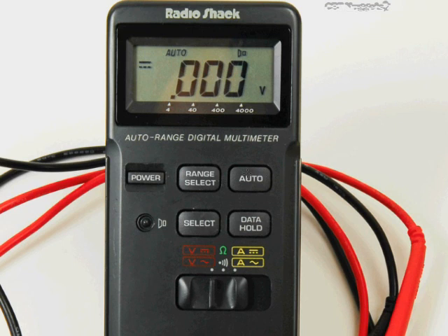You can do it automatically, and the advantage of that is if I make a human error and give it a range that's too low, but I'm testing a device that's very high voltage, it can potentially damage this device. Now, there's actually supposed to be a fuse in here. I haven't actually looked at it. There's supposed to be a fuse in here to protect it against damage. You just have to replace the fuse if you overload it, but I'd rather just use the auto setting.